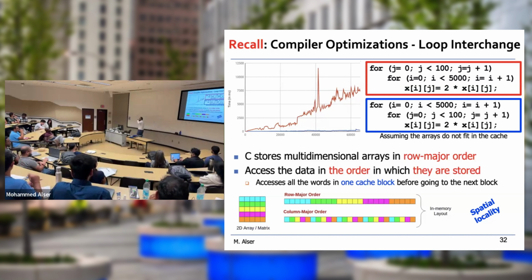So by accessing the first row, all the data in that row already exist in the same row. Although you access column by column, you don't really have to pre-charge again every time you access the column. Now, if we access column-wise, what will happen?